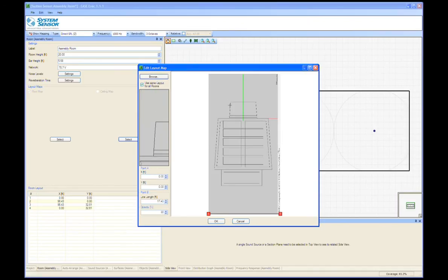Over on the left-hand side, you can see a zoomed-in portion right around where my cursor is. That's very useful for getting these A and B icons that we see down at the bottom here positioned properly. Now we have to position those because since this is an image file, it contains no information about scale or distances. I'm going to take this A icon and move it to the front corner of the room and drop it there. Then I'm going to get the B icon and drag it to the opposite side. Now we've placed two points within our image.